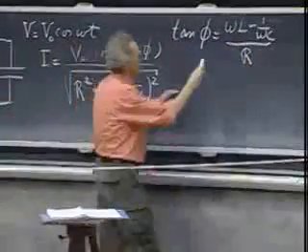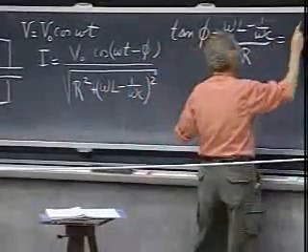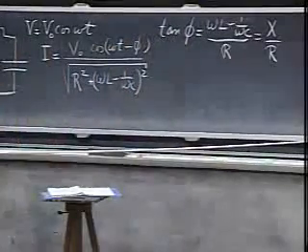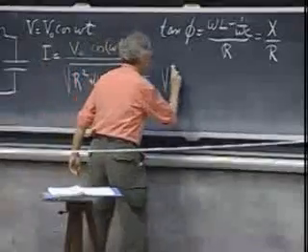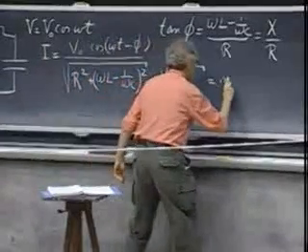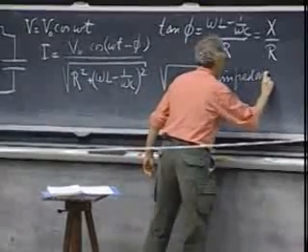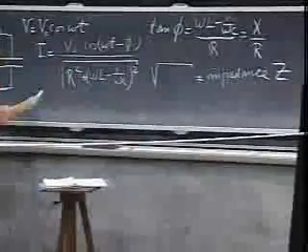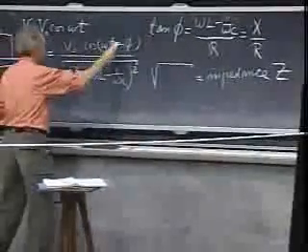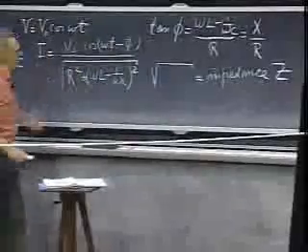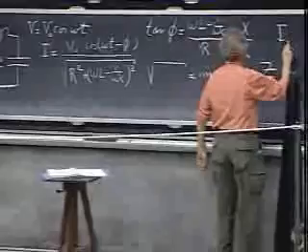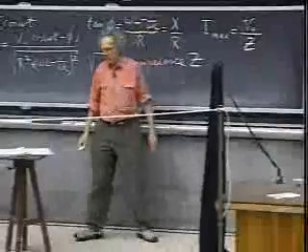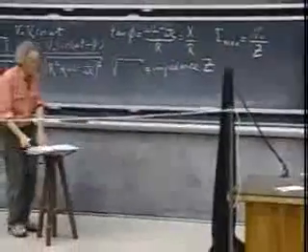We call this the reactance, the upstairs, for which we often give the symbol X, and so this is also X, divided by R. And this whole square root that we have here, we call that the impedance. The units are ohms, and we call that Z. And so the maximum current that you can have, the current is of course oscillating with angular frequency omega. The maximum value that you can have for the current, which I call I max, is then V0 divided by Z. Then the cosine term is either plus or minus 1.